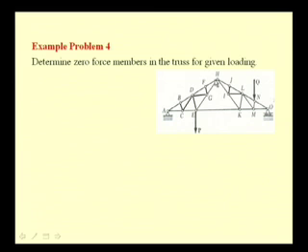The same analogy can be used for this joint at F, where we have DF and FH collinear and FG which is perpendicular to DF and FH. Using the same analogy and discussion, this force in FG is to be 0. We can again see that we have a similar configuration at J, where HJ and JL are collinear and IJ is perpendicular to both HJ and JL. Thereby, this member IJ has to be also a zero force member.